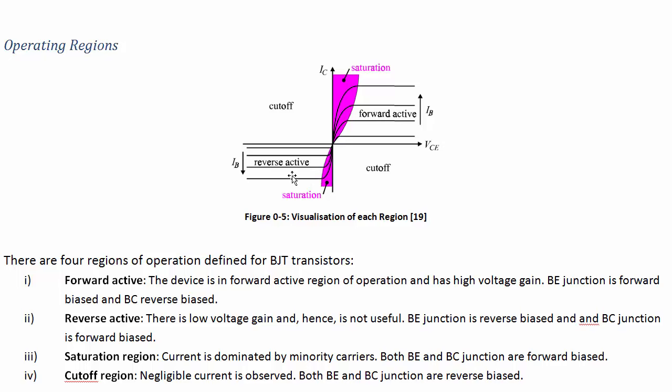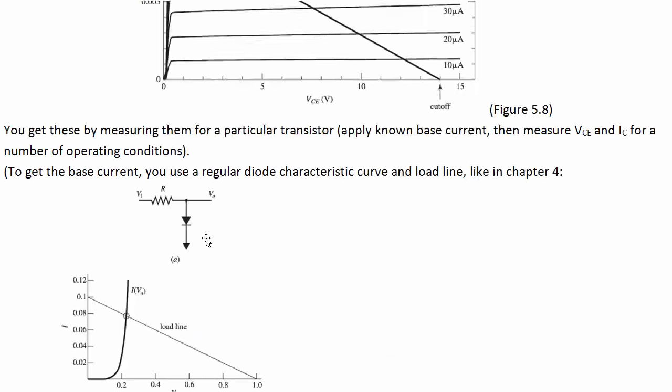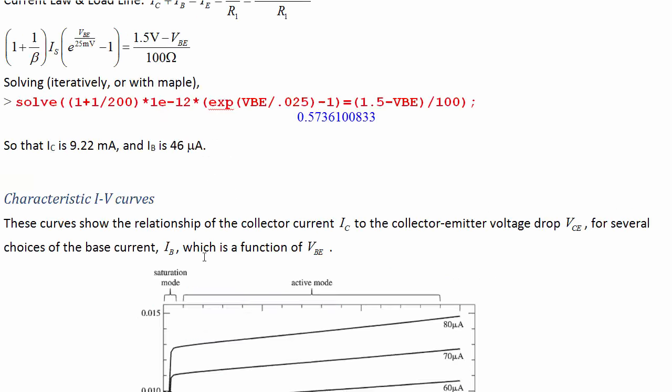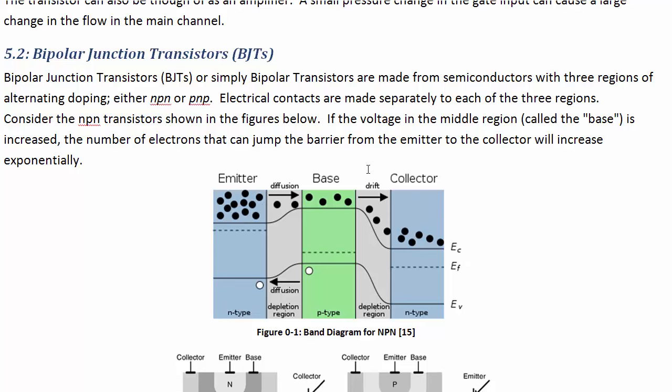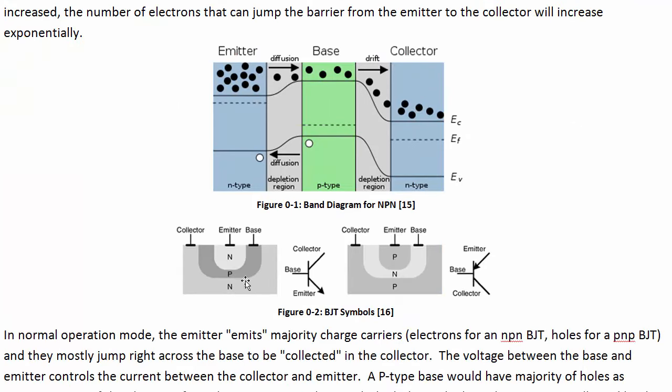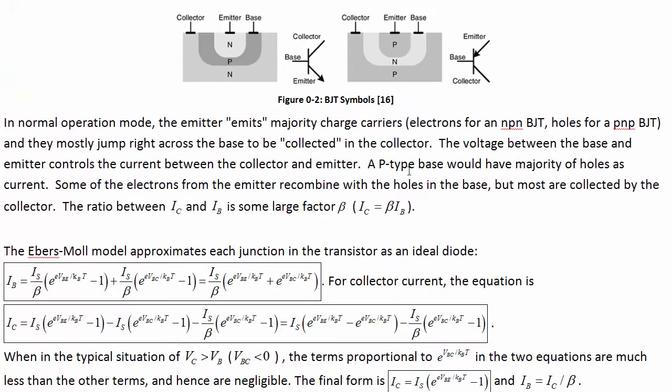So if we have, say, the emitter voltage higher than the collector, you could get electrons to flow in the opposite direction, because then we have sort of the same situation. But because the transistor is not exactly symmetric, it doesn't work quite as well in the reverse region. So you typically get worse gain over there than you do in the forward active region. So it's not a good idea to use the transistor over there.